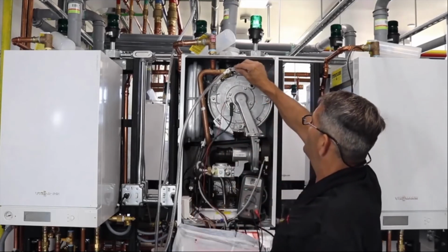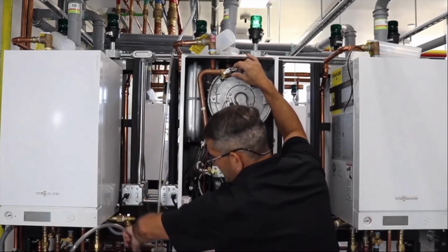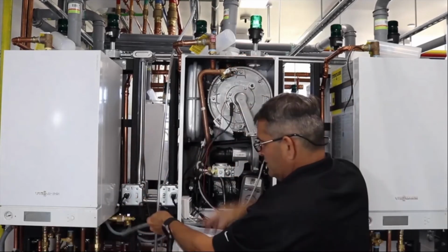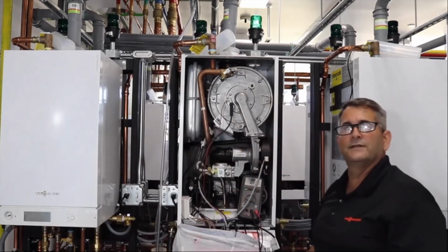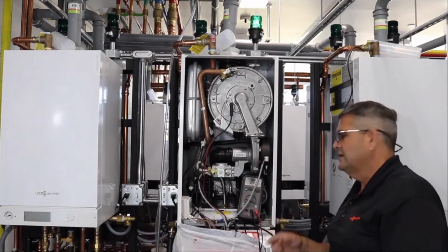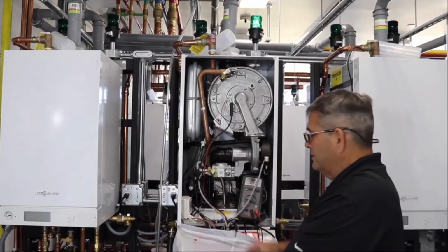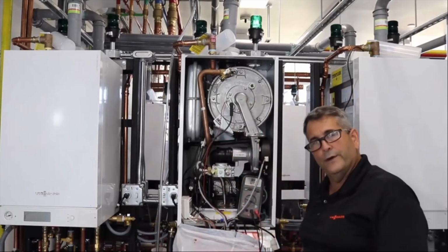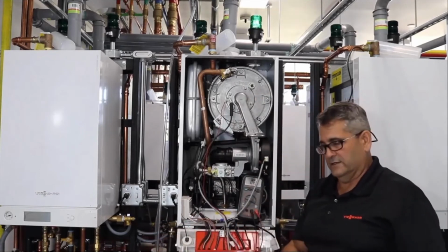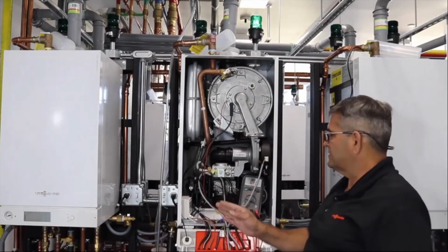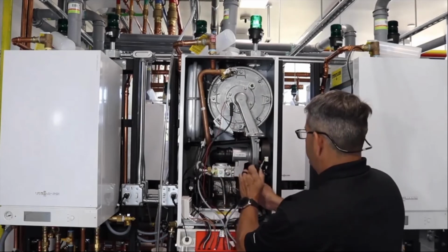Once we do that, we put all our wires back on, we take our hose off here that we bled the air out of. I did have our purging hose here as well, hooked on to the boiler. I do have isolation valves underneath the boiler, so I can shut the isolation valve. And I always purge on the left-hand side because we're forcing that water with the pump through there. And the nice thing with this boiler, if you didn't know, it has that purge mode in here that helps exercise the pump while you're purging, as well as it puts that diverting valve into the center position. Okay, so we put everything back together here.